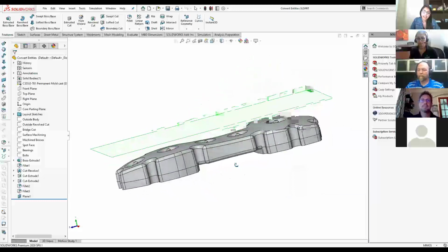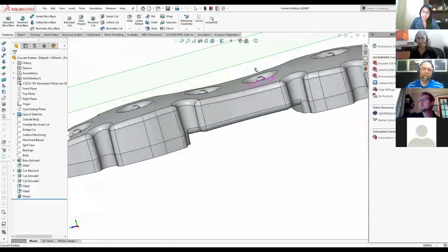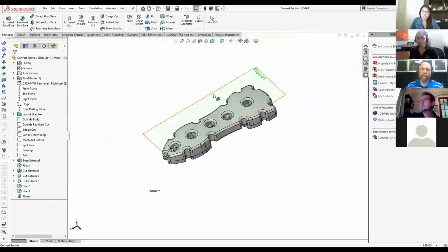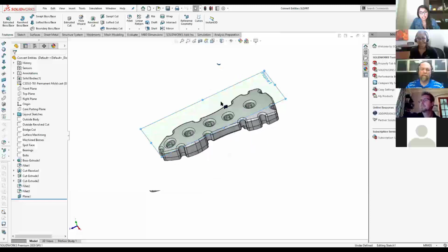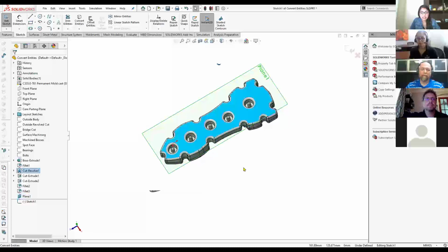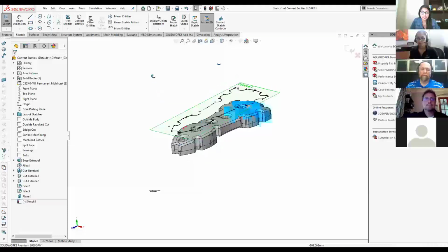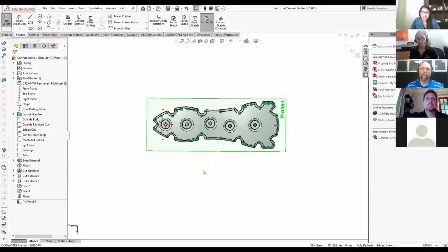I have this convex, very contoured surface here, and I need to grab that geometry and project it onto this plane. So I can right click on this plane and create a new sketch, and I can simply select this face. Notice it's not planar, it's a surface really, and I can choose convert entities. Now, it's not flattening that contour surface, it's just projecting those lines directly above.